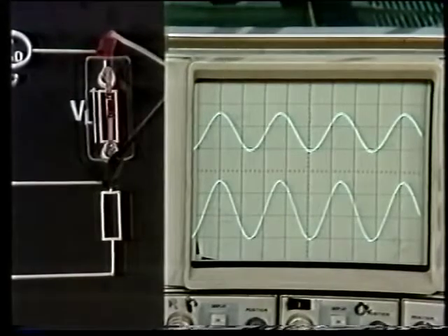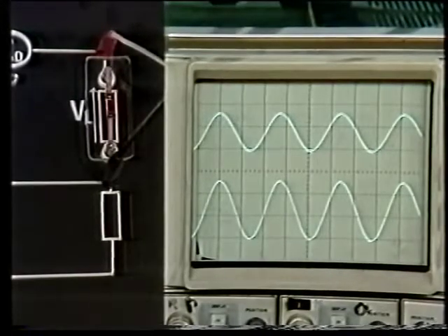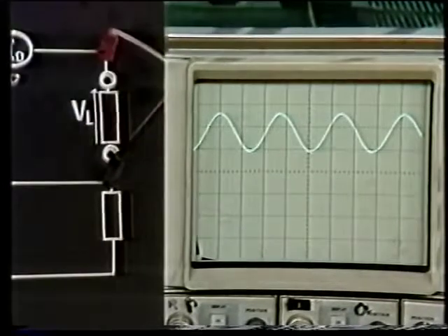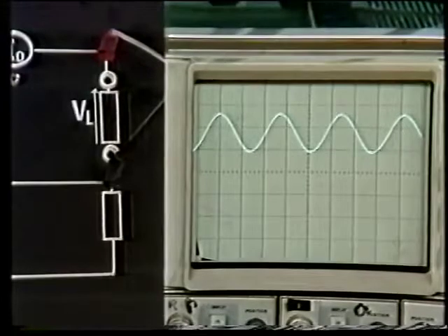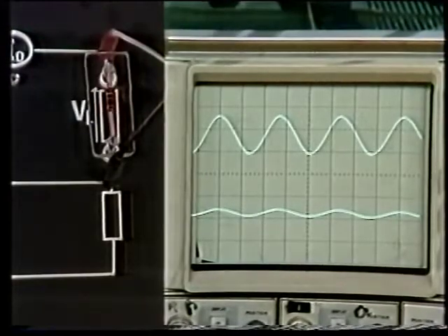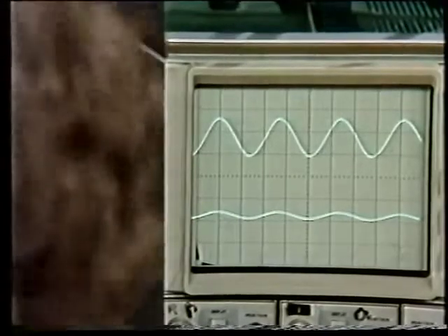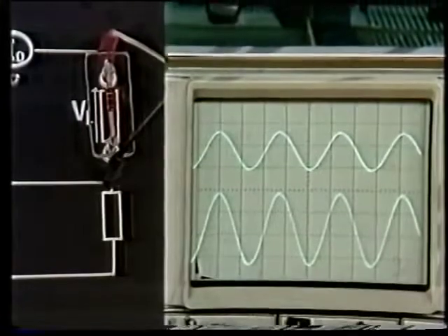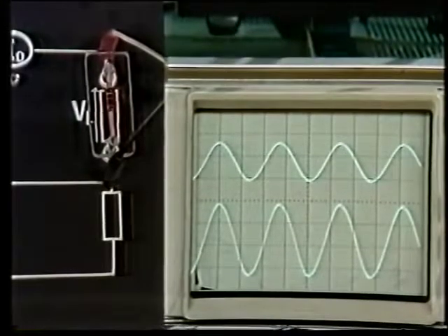And the gain changes by about 10. Now I'll try 100 ohms. And again, the voltage has decreased. And it also looks like a factor of about 10.